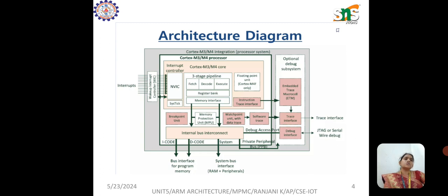The encoder is used in the load and store multiple instruction to indicate which register within the register file is to be loaded or stored. And here we have a mux. Several multiplexers are used to manage the operation of the processor bus. Then you have an arithmetic and logic unit. It has two 32-bit inputs. The primary one comes from the register file, whereas the other comes from the shifter. And you have a status register whose flags are modified by the ALU outputs.